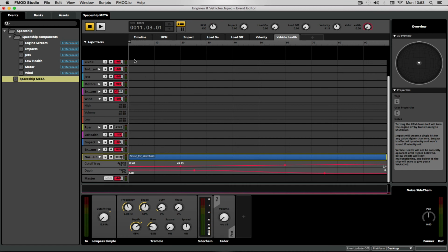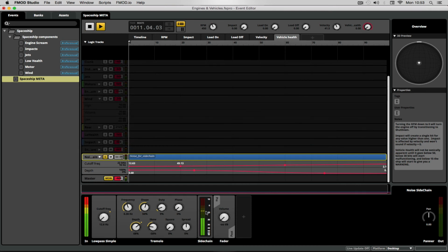Because it has a random amount of every frequency, that's the definition of white noise, if we filter out nothing but low frequency, what we're going to get is a very random modulation of amplitude. We won't be able to hear it because it's muted, but if we have a look at the sidechain amplitude, we'll notice that with no filtering, the sidechain is of course a constant amplitude signal. As we lower the filter down to low Hertz, we start to get a wobble in the amplitude because the low frequency components are coming in and out. And if we go really low down to about 12 Hertz, then we start to get some really interesting fluctuations in sound.